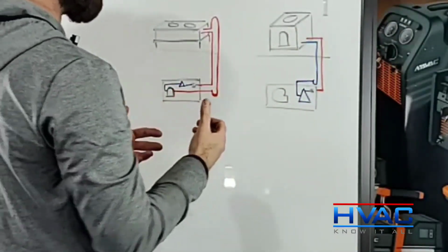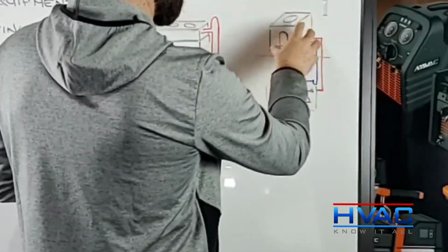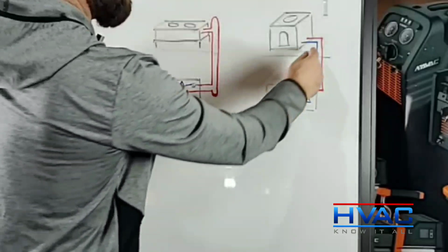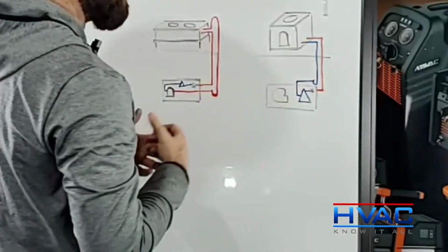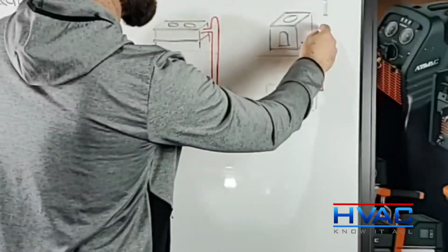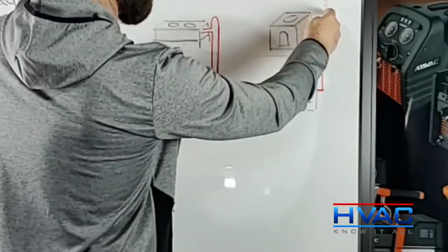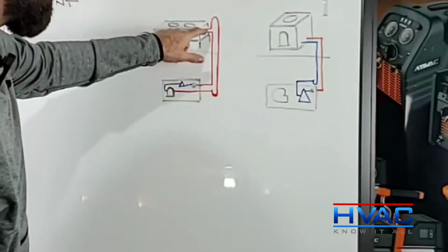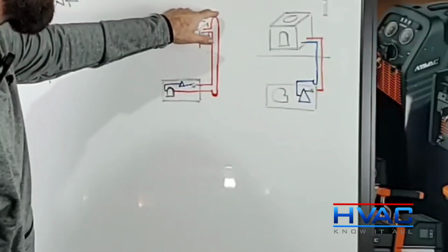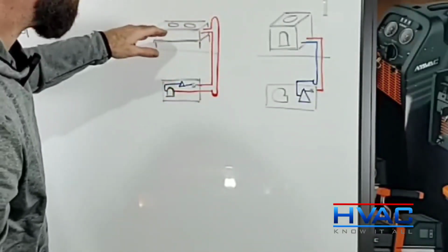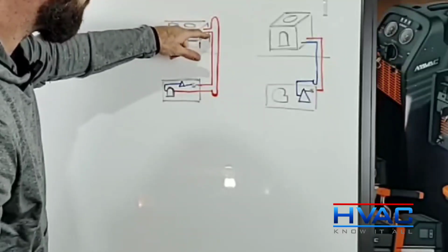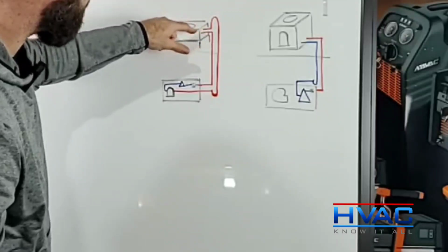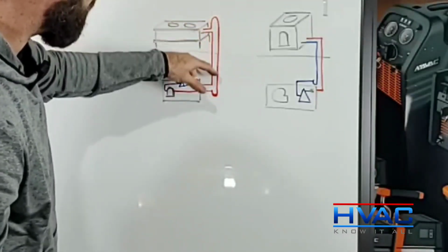But the problem is that a condensing unit such as this, where the piping comes down at the bottom, if the piping enters at the bottom, in order for an inverted trap to work, you really have to come up past the height of the condenser, right? And then go back in. That's why I've drawn it here, above the height of the condenser, right? Because if you have it down lower than the condenser, that oil can still get back. But if it's up, it's not going to lift and go back down.